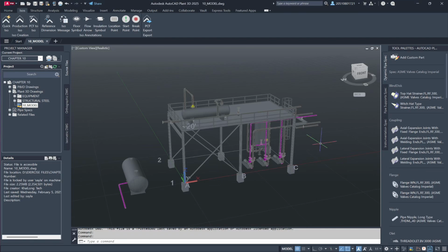When routing piping throughout a facility, there are instances where we must establish its position relative to non-piping elements. These elements typically include buildings, structural components, pipe supports, pipe racks, or modular units. To achieve accurate placement, a reference dimension can be incorporated into the model. This ensures precise alignment with non-visible components.